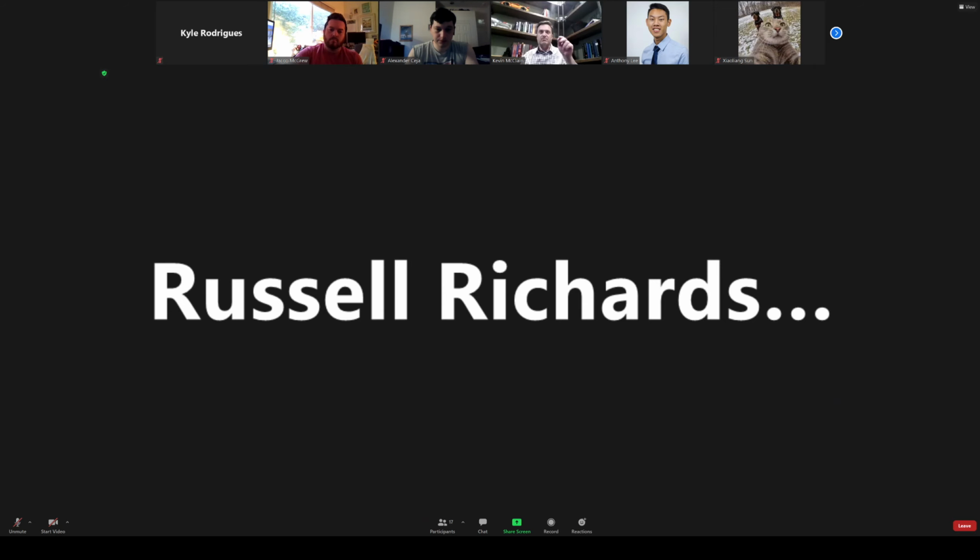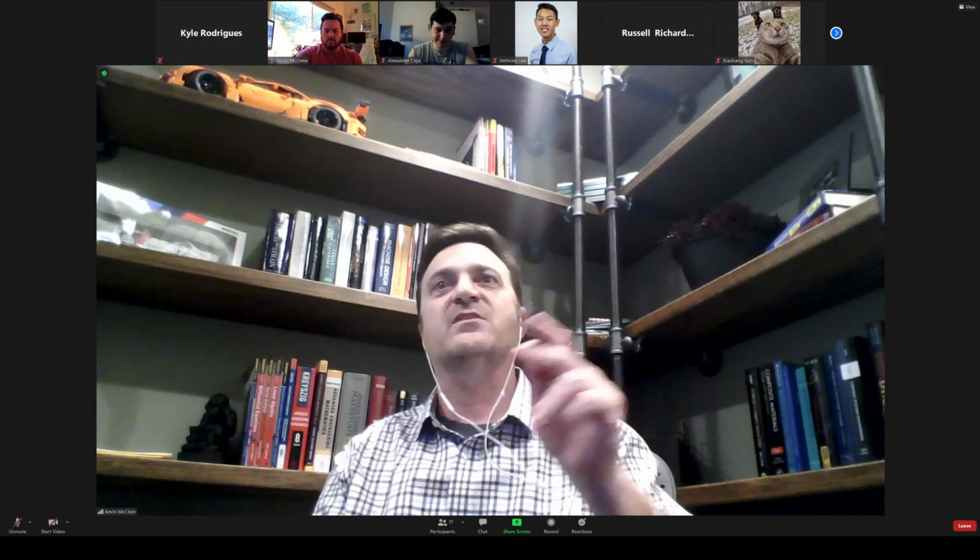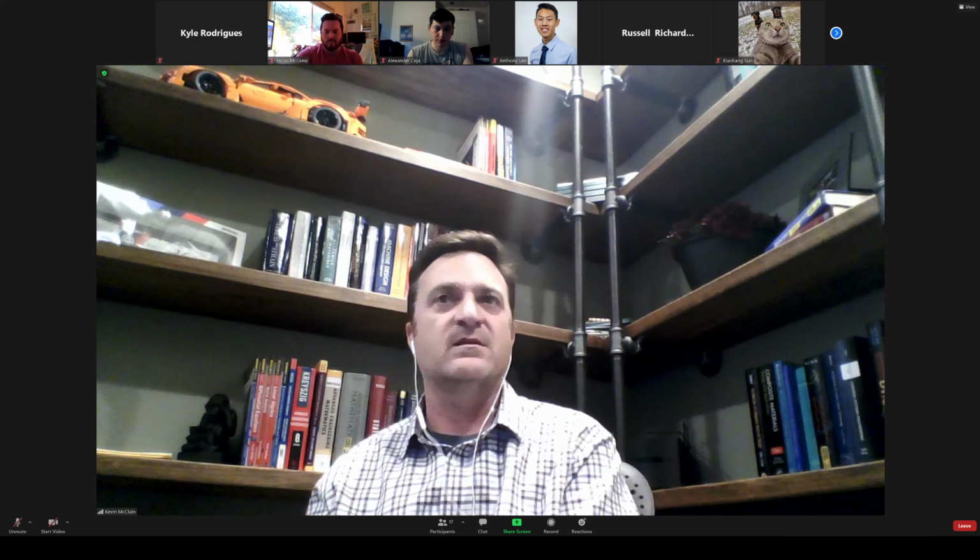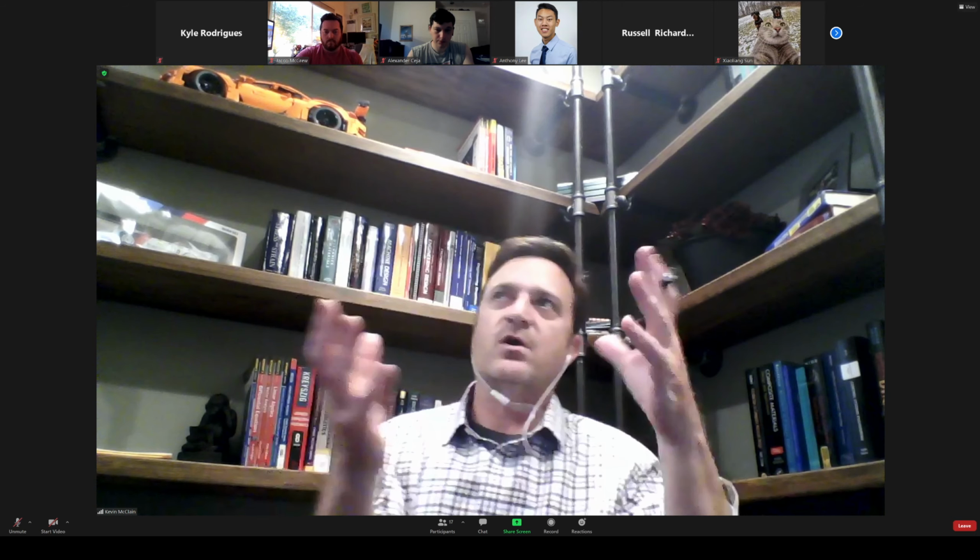And remember the terms in that are those B terms, and those B terms are a function of the shape function, weight functions, and all those. So if you have some crazy functions in that B matrix that you have to solve as part of your inversion, it's going to take forever. And then you have to figure out how you're going to split this up computationally. Are you going to use a GPU to do some of that processing? Is some of it done on your local CPU? Then you run into local RAM issues, depending on how much you need and how the code is handling storing that for the solution, because it's going to store all of that information in local RAM while it's accumulating more and more, trying to get the solution. So your processing time goes through the roof.